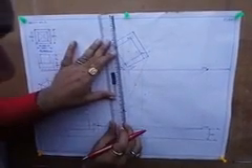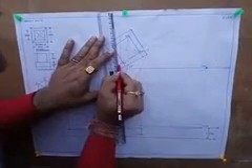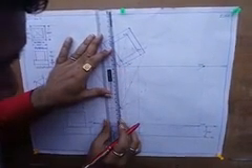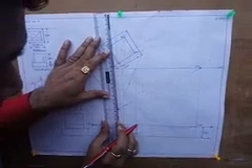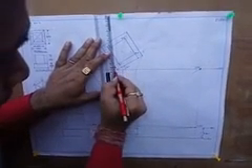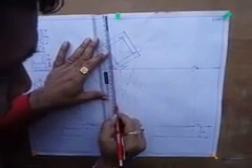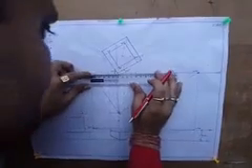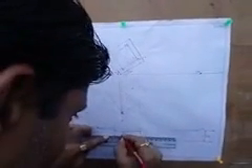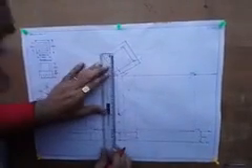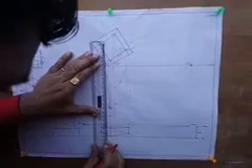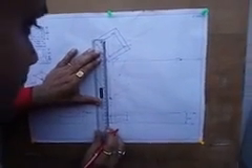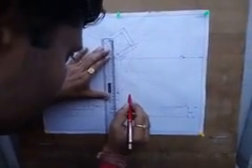From the 1 1 dash which is transferred to the left edge, draw the line from the transferred point to join the station point. Okay, then from this, draw the reference line to the bottom.